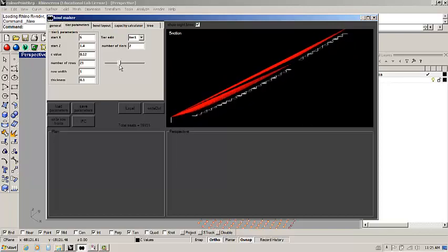This is just to demonstrate future functionality. It makes it a little bit more dynamic in adjusting the parameters, to have a slightly more interesting user interface. And we can change the row width. This thickness is a concrete precast dimension. I'm not going to change that. Then I'm going to go to tier 2. I'm just going to make a small adjustment to the number of seats, and then pull that one forward by 3 meters.